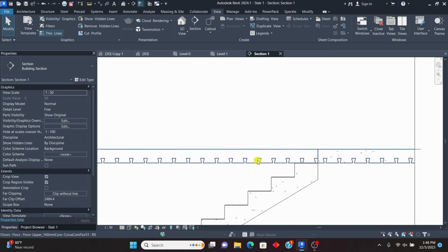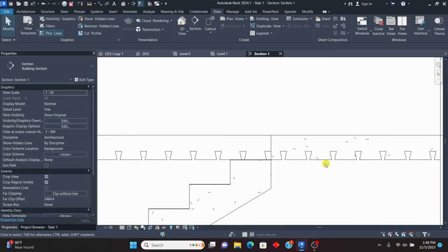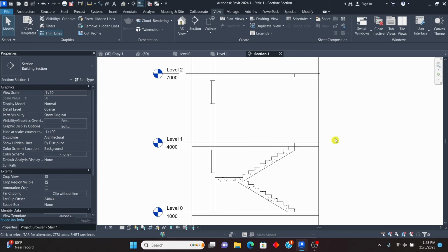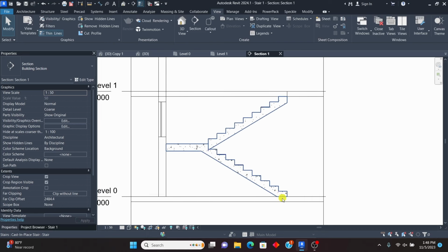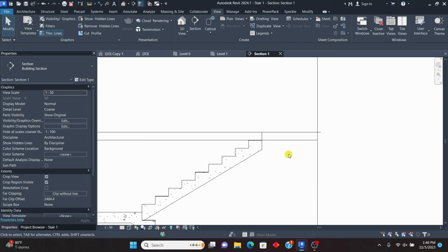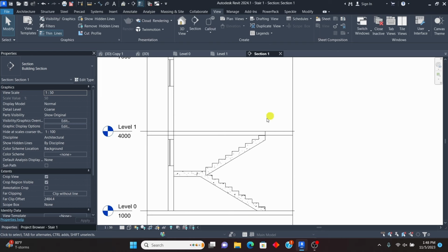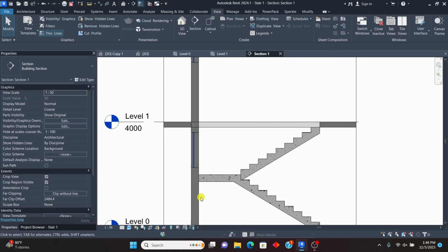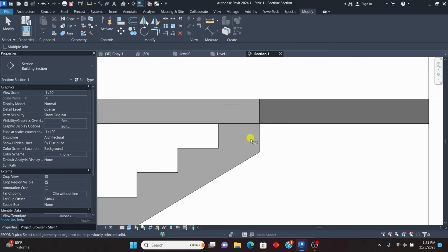Actually, the slab that I picked is the one with that metal at the bottom. I can change that one later, but I just go to coarse so that it just shows that it's concrete, which is okay in terms of detailing. I can change the actual slab to concrete if I want, but I'll leave it the way it is. Once we have this, let me also click on shaded so that I can change the graphics a bit.